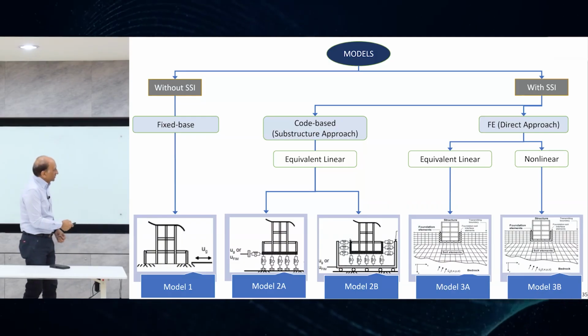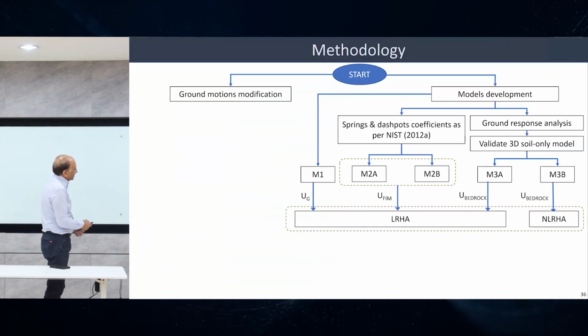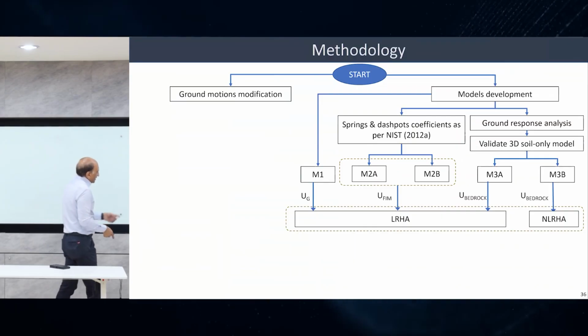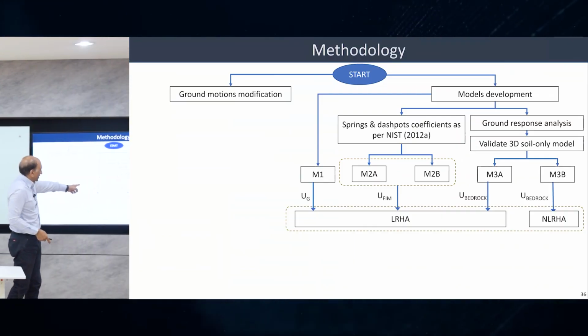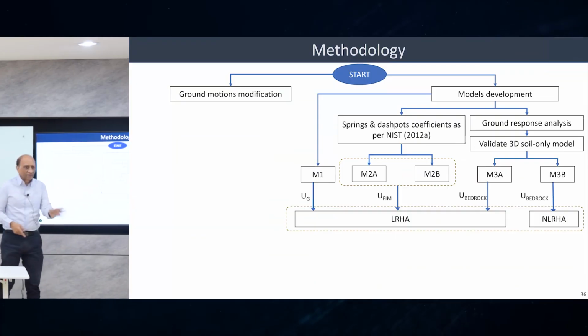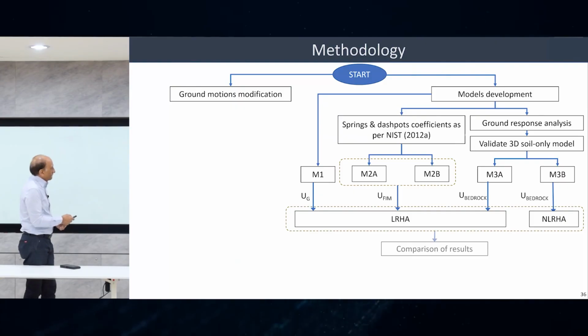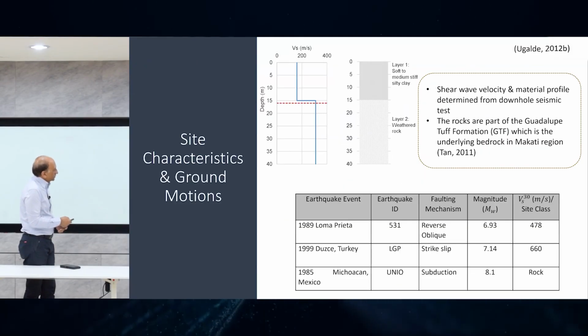Okay? So that's what she did. The rest is a lot of details. She performed linear time history here, nonlinear time history over here, bedrock, ground motion, 3D models, a lot of work, and then compared the results from there. So she took many ground motions and tried to apply them all the way through the soil.